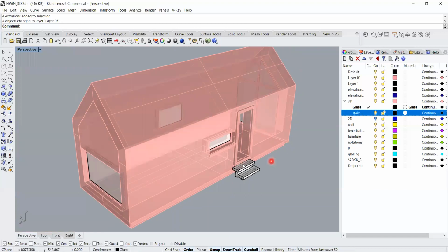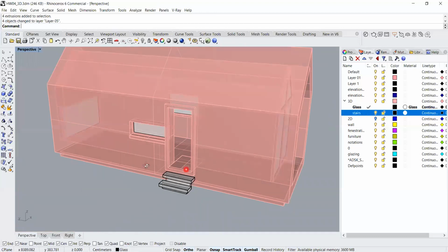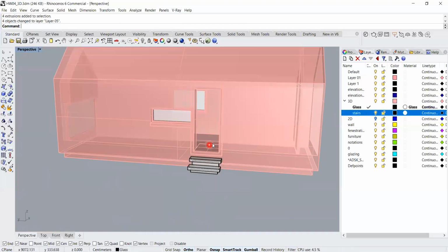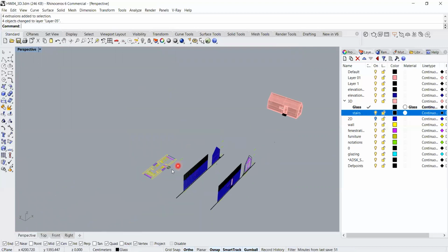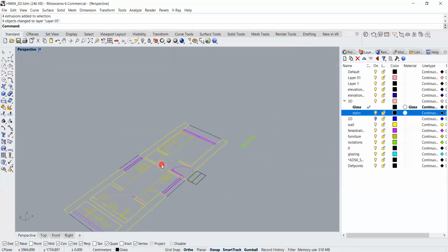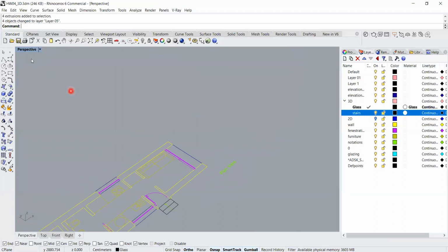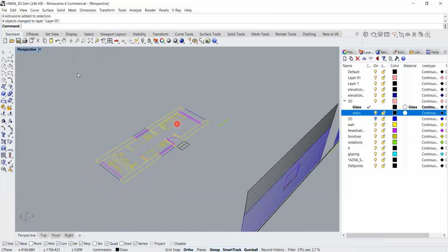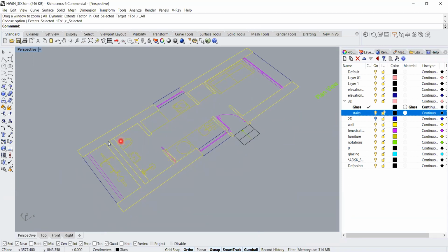So what remains is only the inside partitions of the buildings. So how can I do that? I think in your fifth homework, homework 5, you had that loft shelter. So what you can do is similar to that. You can come to plan view. What you need is just to extrude the walls coming outside of your ceiling, your roof, and then you can boolean it.